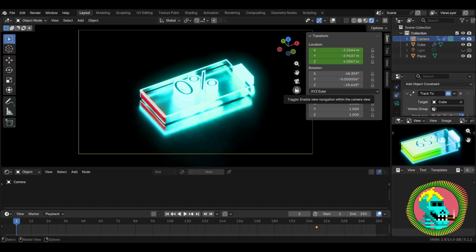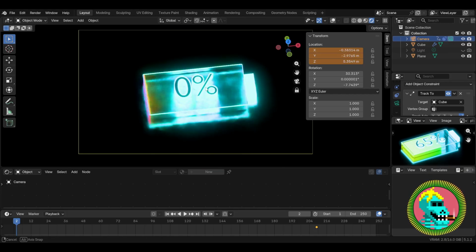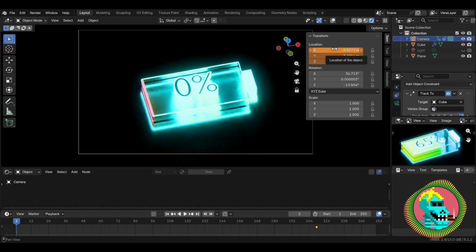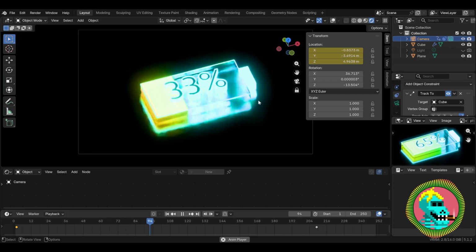Our view is also blocked. And select the initial animation view. For example, like this. Let's hover over the location field and press the I hotkey again to create another animation key. And now, if we start watching, we see that we've got some animation.